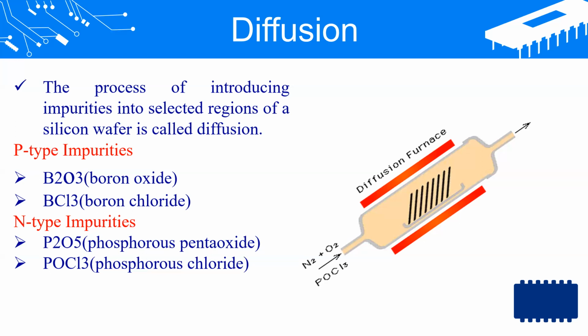The dopant can be added into the silicon wafer by using one of the most commonly used methods. One is diffusion from a chemical source in vapor form at very high temperature. The second one is diffusion from a doped oxide source, and the third one is diffusion from an ion implanted layer. A schematic representation of the diffusion process is shown in this figure.